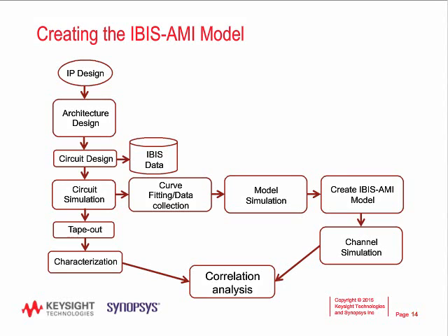To achieve high model fidelity, the model should respond similarly to the circuit response, so circuit simulations are run and parameters are extracted that fit the algorithmic response to the circuit response. This is the curve fitting or data collection step, and consists of generating data model parameters such as poles and zeros for the CTLE, bandwidth measurements, and other non-idealities of the PHY. After the curve fitting data collection step is completed, the model is simulated and the response is verified versus the circuit response. This is the model simulation step.